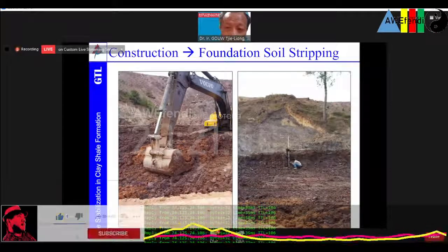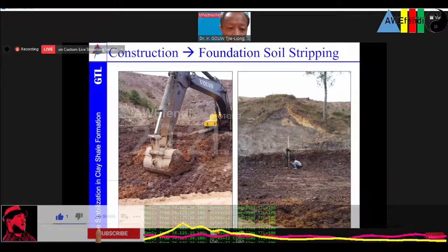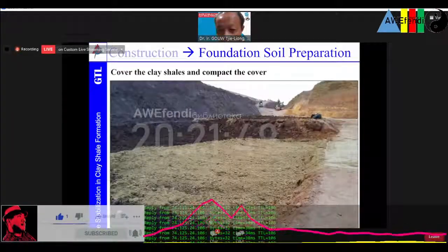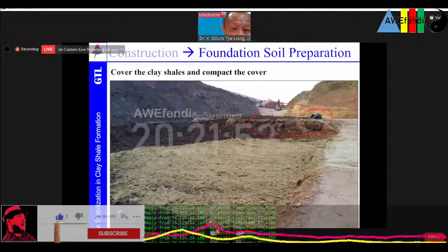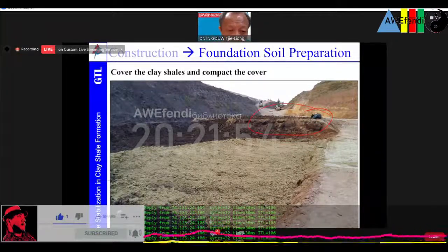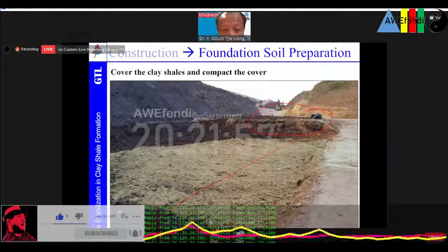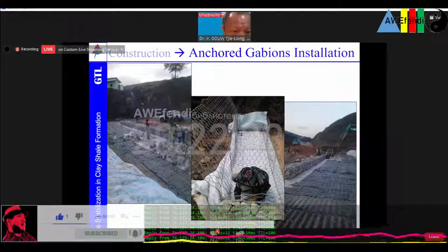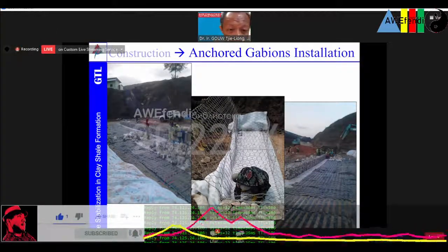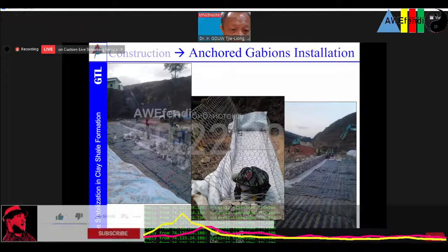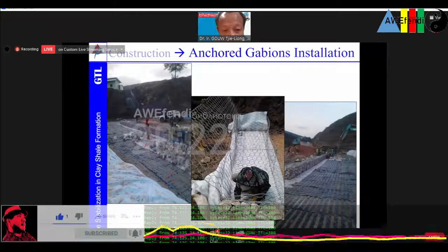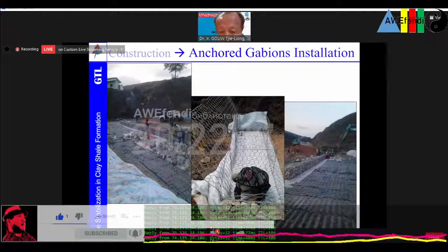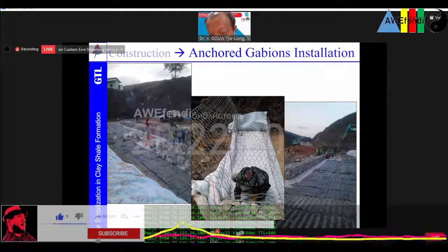Every excavation is not very wide. You see over there, we stop there. Over here, we excavate. Then we start building up, first covering at least the first 1 meter like this. So lay the geogrid, and lay the geotextile in front over here, as a separator, to prevent the fine grain we put over here and compact from intruding into the gabion system, causing loss of particles. Of course, we have to put this non-woven geotextile.